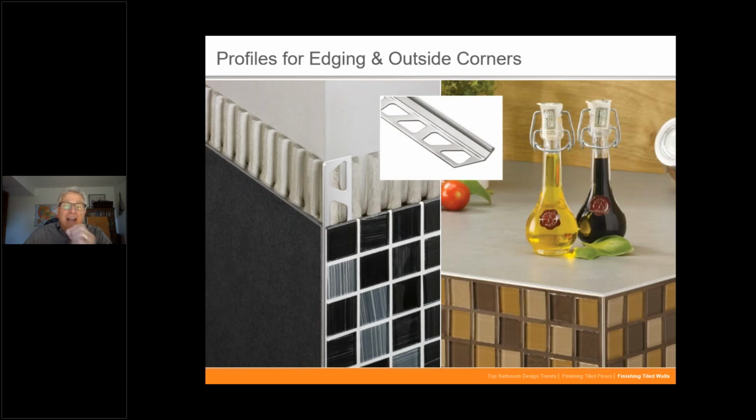Here's that very fine edge one that I showed you earlier. It's really hard to see it when the tile is installed and grouted, but you can see that it's exposed above there to show you that that is actually a profile. Those tiles are vulnerable. If they take a hard blow or a knock, it could actually chip a tile. So that's a good idea to put those in there. I know a lot of tile installers like to just back cut those tiles on their tile saw and put a miter on the backside and slide them up there. And that may look good for a while if they did a very nice job, but this is going to ensure additional support and